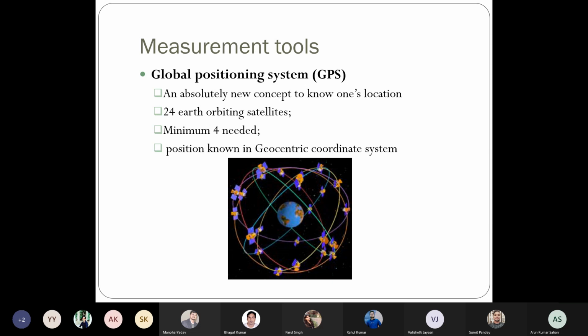If you recall the coordinate geometry concept, then we can connect the unknown point to the known points' coordinates. Once the known points are connected with the unknown point, just measure the distance. What is the distance of point P1 from P0? P1, P2, P3 are the known points, and P0 is the unknown point. So measure the distance between P1 and P0, P2 and P0, and P3 and P0.